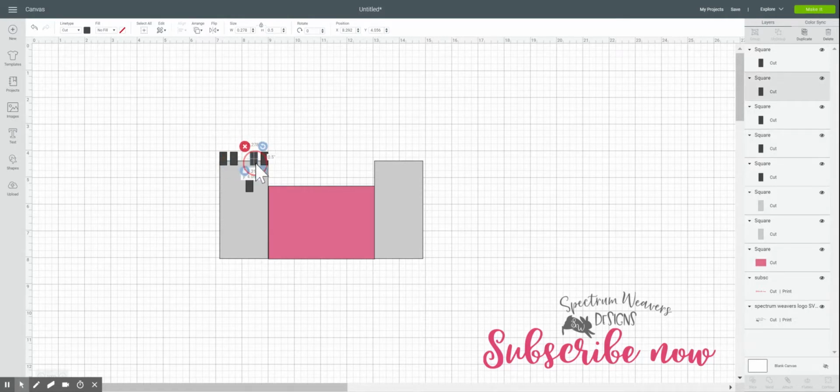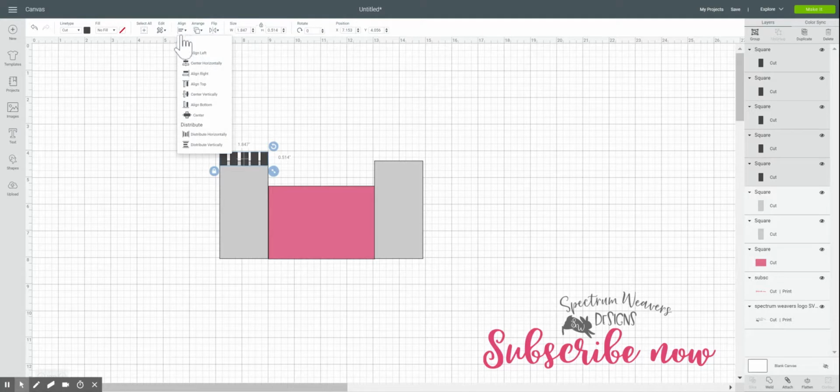You'll see in a minute, we're going to evenly space them out. Okay? So what I want to do is draw a box touching just those. I don't want to accidentally select this. Okay, and now I'm going to go to a line, and go to the very bottom here where it says distribute horizontally, okay? And now they're all equally spaced out.